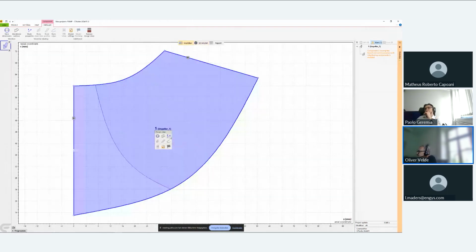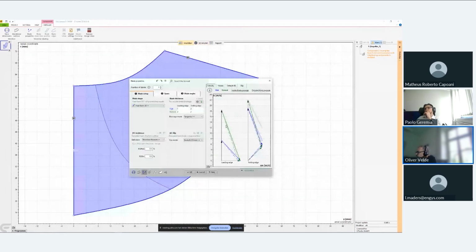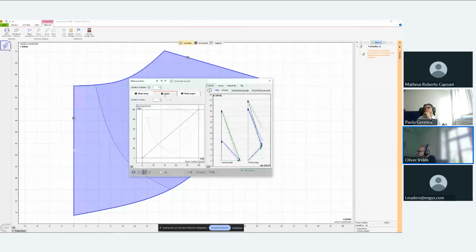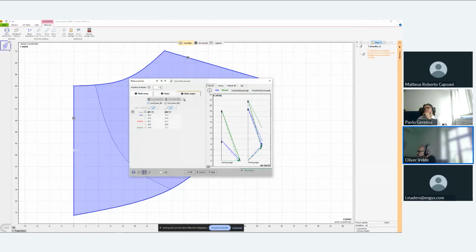The next design step is to tell what is the general shape of the blade, what's the number of spans I would like to design the blade on, what's the number of blades, and what are the leading and trailing edge angles. Again, we make proposals if we are in the automatic mode or if we press the calculate button. And again, we apply empirical knowledge, like, for instance, the slip model for the trailing edge and the Euler equation for the calculation of the trailing edge angles.